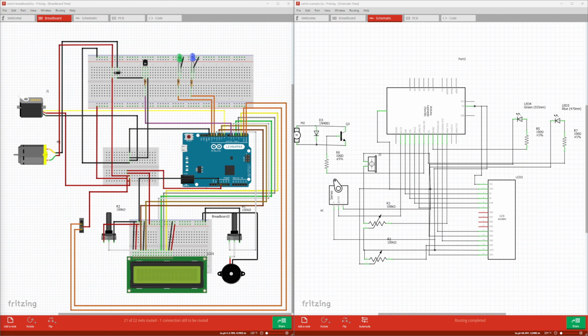There are 6 component areas of interest here: the switch, the piezo buzzer, the potentiometers, the DC motor, servo, and the LCD screen. Let's start with the switch. A switch is a single pole double throw switch which produces 3 states, which is what the program is based around. The switch works by connecting 2 different leads to power or neither, and we can measure this.